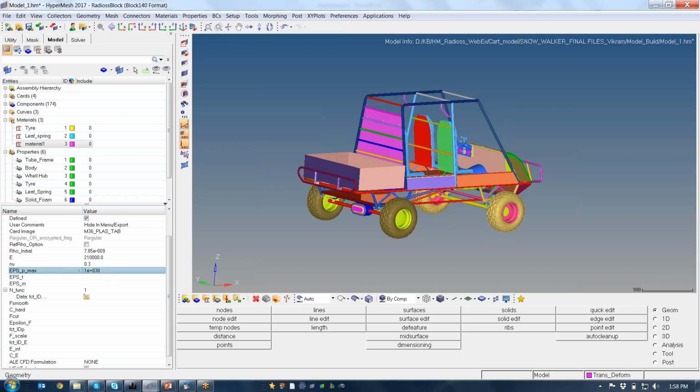The other data you can specify here is not mandatory. You can specify, of course, after what strain the element has to fail. This is a very crude, very basic way of representing rupture. Rupture in a structural member is a combination of strains; the material will have a different failure strain in tension, in compression, and in shear, and it will also be affected by the strain rate. So rupture is a complex physics. With this option we are not getting into that complexity.